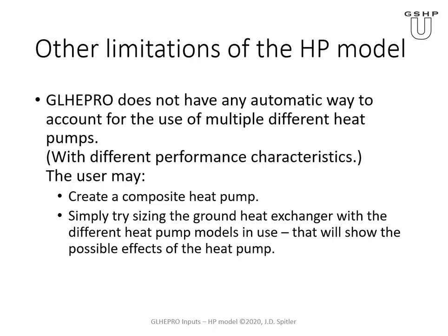And then if you are really concerned about improving the accuracy, you could actually take an iterative approach. So you assume a set of temperatures that the heat pump is seeing, and whatever the heat pump does, you calculate the heat extraction and rejection rates. With those, GLHEPRO can give you a new set of entering fluid temperatures, and you could use those. So it's possible to do a quite complex model, but it's somewhat tedious, I would say.